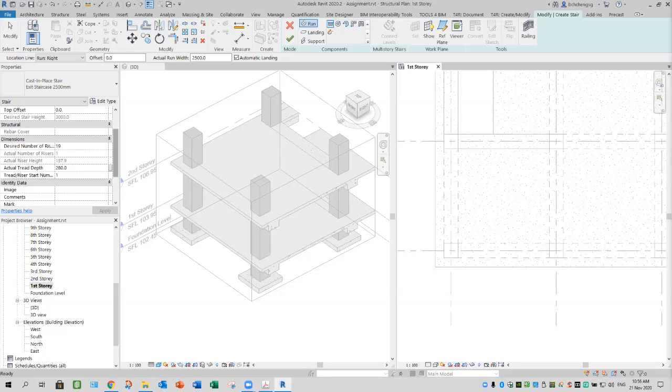Since it's a 19 stair flight, if you want to divide into two even flights, that means this side goes up, this is the return. Not return, you have a mid landing, so make it even, either 10 and 9.